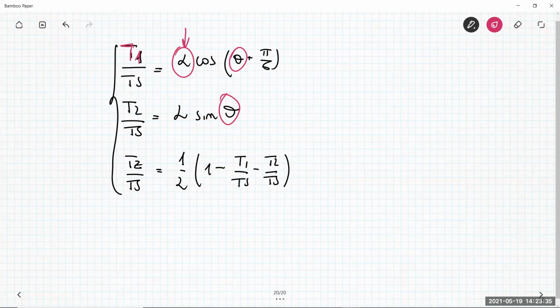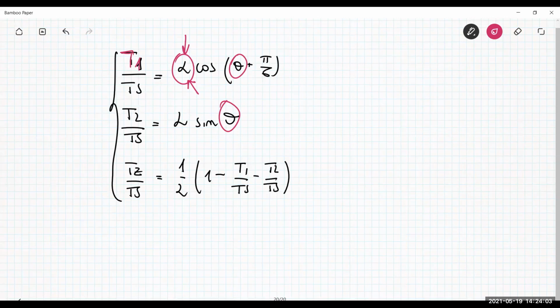If you have questions, I can answer your questions. Tomorrow, I want to stress a little bit which is the maximum possible amplitude I can get at the output. So I will stress my explanation about this alpha coefficient I considered here. And then we can investigate a little bit about the symmetries I just mentioned before to make possible the minimization of the dynamic power, and to make possible to eliminate the high order harmonic content of the output voltage.